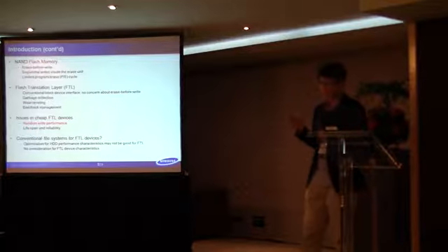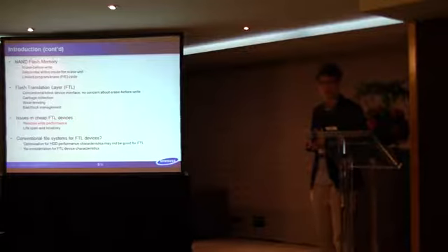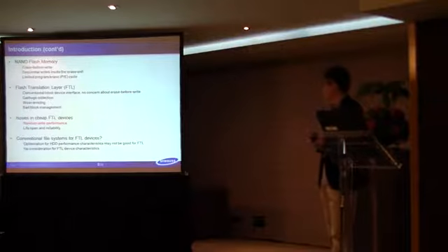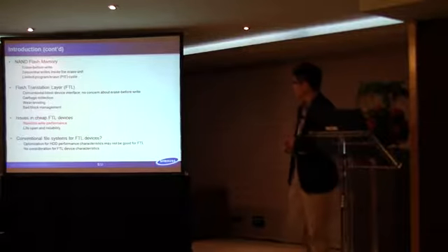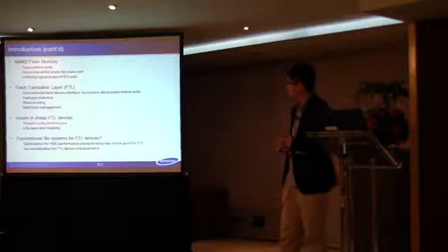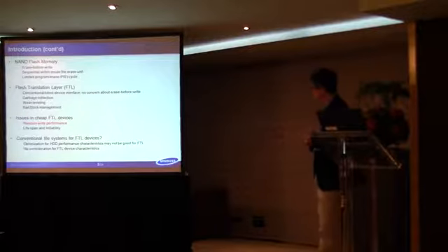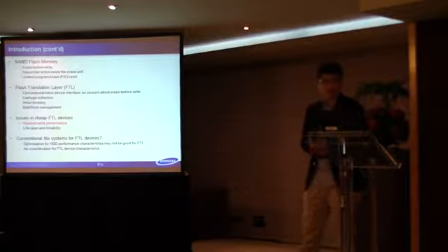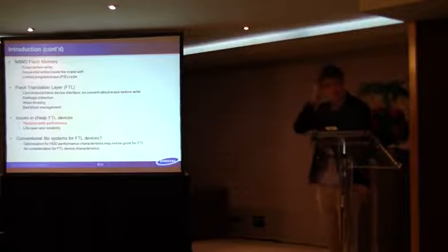We have only a very small memory footprint to use for the FTL running. So we end up with poor random write performance, and it also causes a lifetime limitation. These two problems are major issues in FTL device design.